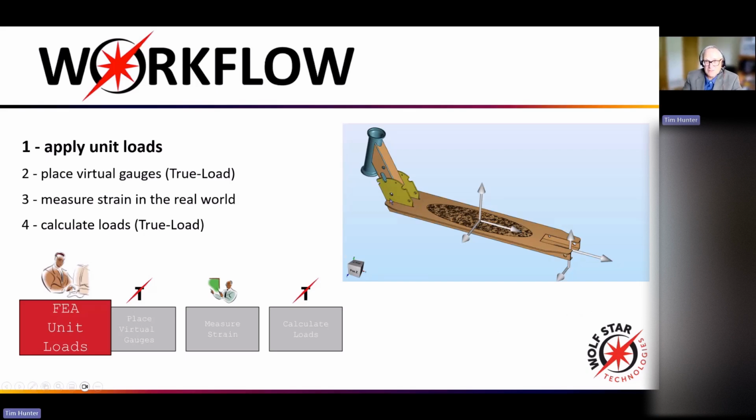So these are just your FEA models, okay? You set up your FEA model any way you want to. But rather than putting in a complex load on your model, I'm going to have you decompose it to a series of unit loads. So like on this Razor scooter, I put in 1 kilonewton XYZ at the foot, and 1 kilonewton X on the axle, and 1 kilonewton Y and Z at the tire patch, okay? So I've got these 6 unit load cases on my FEA model.